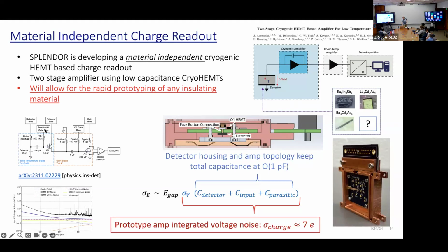And then it's set up in a voltage buffer configuration called the source follower amp. So all it does is mirror the voltage at the input to the output, and it buffers all the upstream capacitance from all the cabling. So by running that HEMT down on the mixing chamber of the fridge, we don't have to worry about any of the cabling capacitance. And we've gotten the entire capacitance down to about 5 picofarads for the whole capacitance budget.